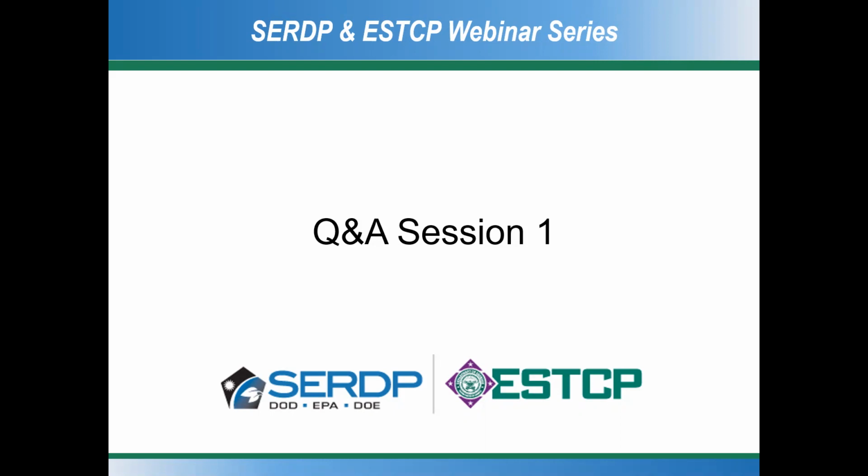I would recommend potentially some geophysics work, but also a fair amount of borings to understand what you're dealing with. A lot of soil work, a lot of collecting samples to understand the media in the subsurface. So again, I caution: I think this is a great technology, but be careful using it in situations where you may not know a whole lot about the site. It's something you can't just jump into.